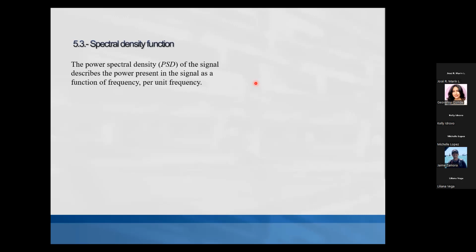When we see a peak in this function, PSD, that means that for that frequency we can expect a lot of contribution to the total energy or power of the wave elevation. That means you can expect that in this region of frequency the wave is going to have a large amplitude.